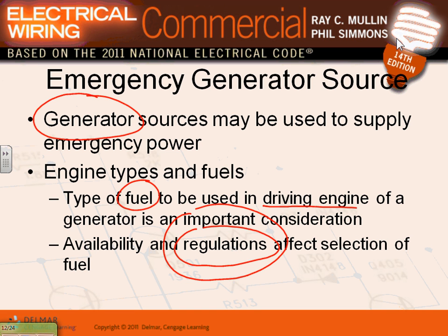So just remember one thing: if somebody says I want a generator, ask them, is it an emergency generator, legally required, or CUPS, critical operation power system, or hospitals? Is it one of these? Yep, then we're safe. If it's a standby generator because we decide to, we want to just run continuous on diesel, you better consult the EPA requirements.